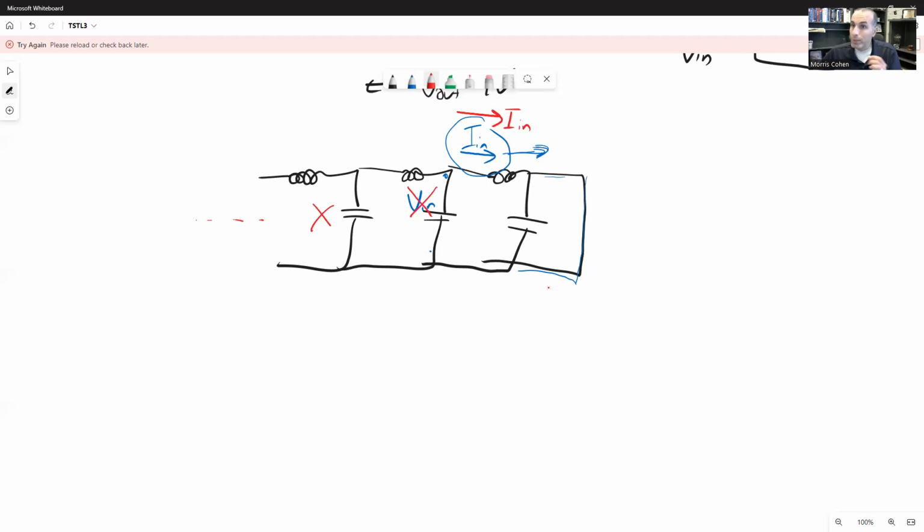So this appears to be the opposite, in that we had 1 volt that was sent out to the load, and the load says, I'm not allowed to accept any voltage, so the only way to make the load happy, while also obeying the transmission line need to have voltage and current have the same ratio, is to launch a negative voltage back in the other direction.